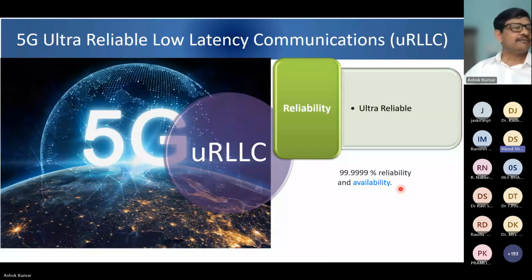Sir, interruption should not be there. There should be complete redundancy in the network. Correct. That means if I have one device, it should be able to connect to more than one BTS in parallel, and parallel transmission of data should be possible. So dual connectivity features should be there, so that it connects to more than one. And from the BTS perspective, it should have a redundant backhaul towards the core. If one fiber gets cut, the traffic should continue on the others, right?